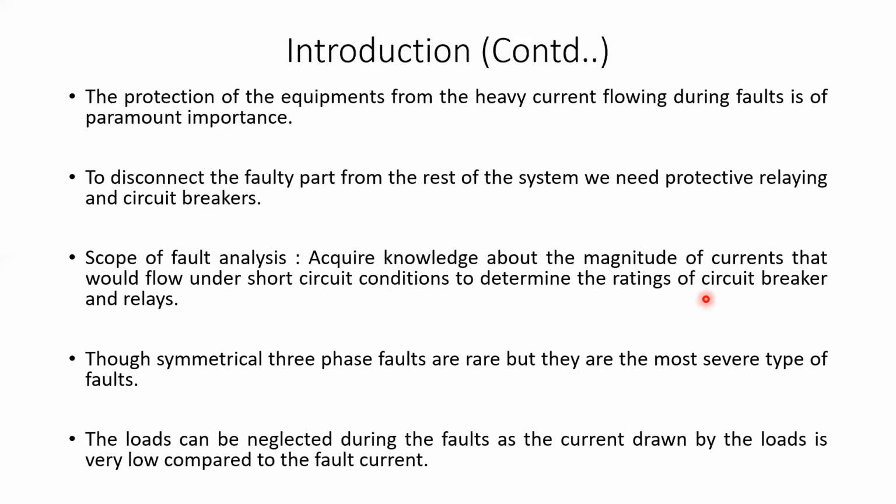When we analyze a circuit for a fault, we can neglect the loads. The loads can be neglected as the voltage dips so low in case of a fault that the current drawn by the loads is negligible compared to the fault currents. So for better calculations and for ease of calculations, we can neglect the amount of current drawn by the load in case of a fault.